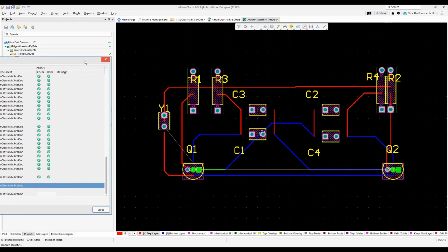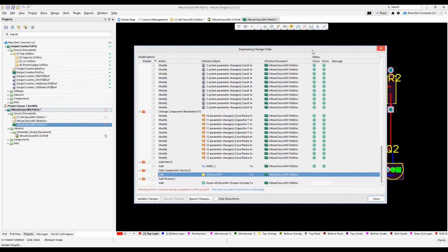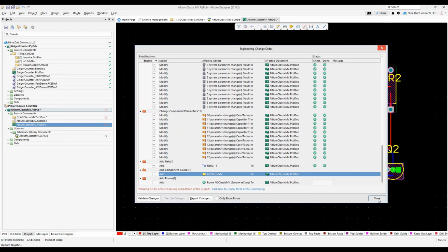So remember, we changed out the symbol, and if we changed out the symbol, or actually the component in the schematic, we're also changing out the link to the footprint. So all these footprints came from our Altium 365 account as well. So we turned this into complete hash as well. So that's kind of the sticky point that you get into with something like this.